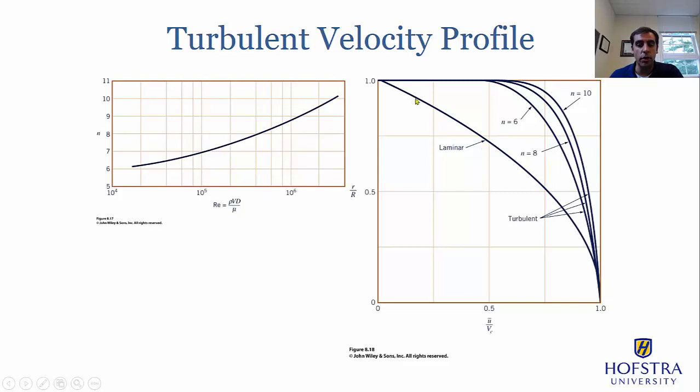And if the flow were turbulent, there was no analytical solution. But what we saw is that because of the mixing that exists, because of the turbulent eddies, you have a much more uniform speed throughout the majority, or the center, of the pipe. See how this is staying relatively constant for a while. And then there's a sharp gradient at the wall. That sharp gradient at the wall gives us high shear stresses and high losses in pressure.